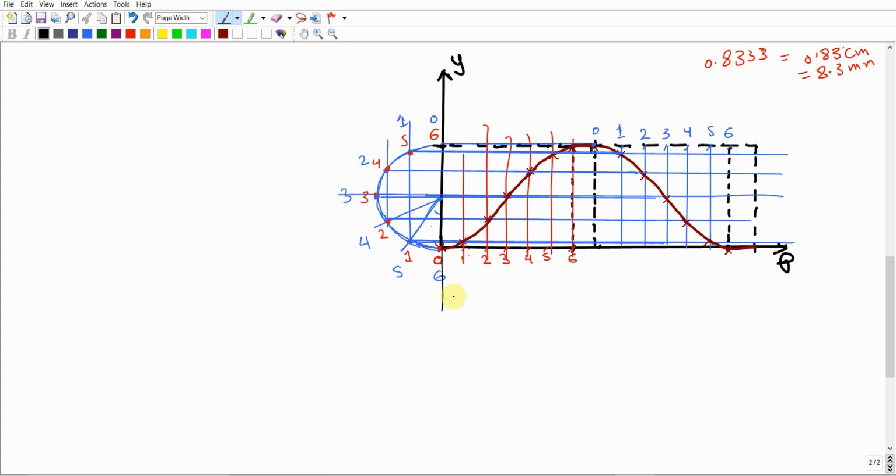Then you're just gonna draw another horizontal line that is parallel to the theta axis, and you're gonna divide over this line, because the original theta line is already crowded, as I mentioned, with so many things. Then you're just gonna measure 1 centimeter starting from the 0 point. This is gonna be the first point, which is just gonna be the 0. Then you're just gonna start to mark other points.